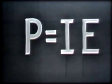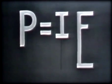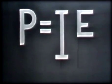Since power is the product of current times voltage, the increase in voltage by means of the transformer must result in a decrease in current. And likewise, a decrease in voltage by the transformer must result in an increase in current. Now, stating it another way, we can say that a transformer which increases the voltage by a given ratio will decrease the current by the same ratio, and vice versa.